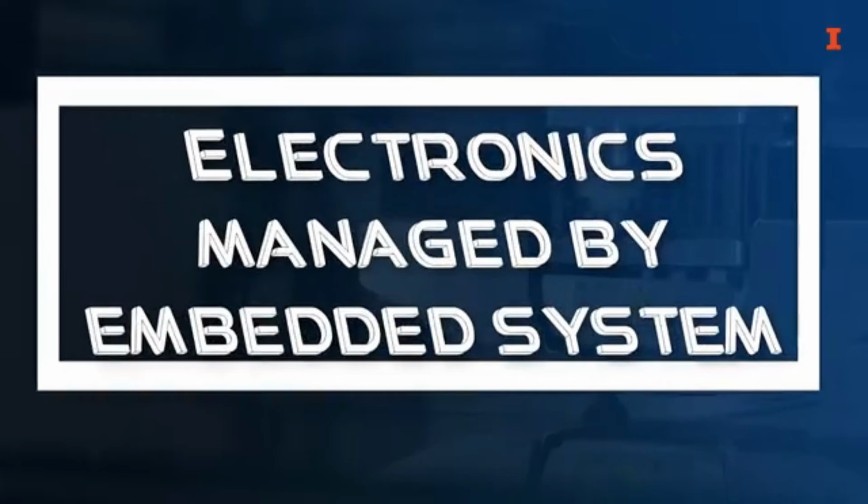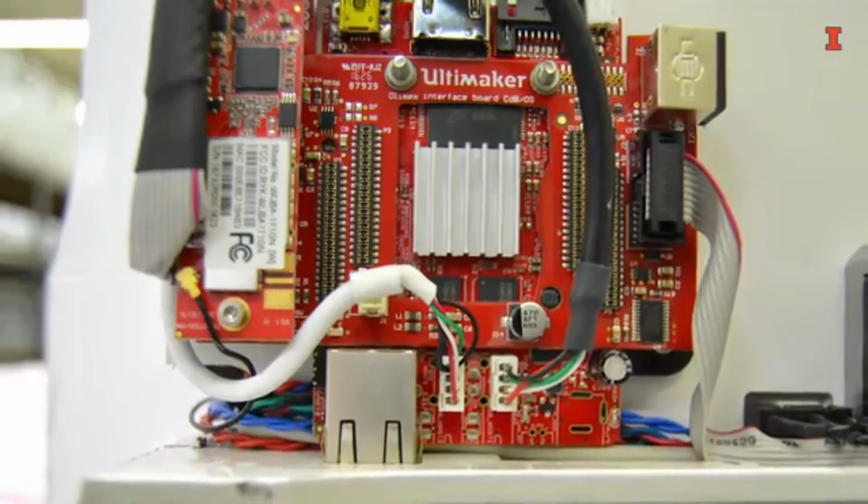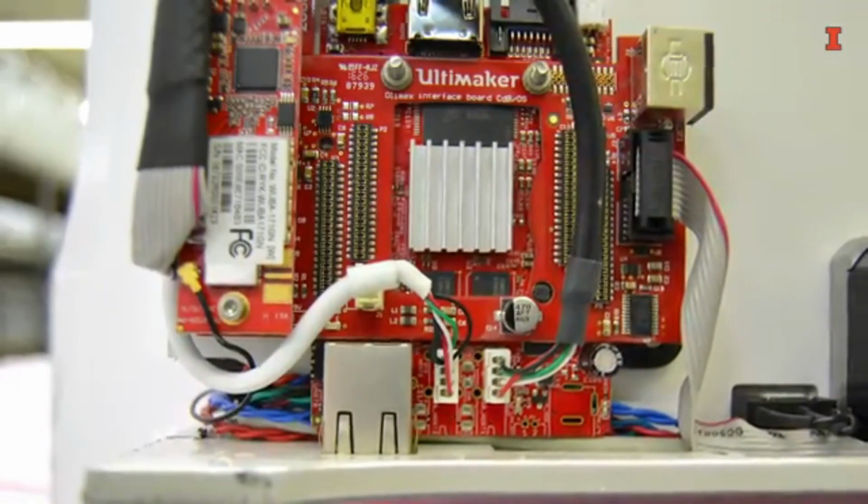In the case of the Ultimaker 2 electronics, the 3D printer control electronic subsystem consists of a main board, power supply, and routing, XYZ stepper motor controllers, extruder motor controllers, heater and print part cooling fan controllers, heater and temperature monitoring, as well as many more like bed heaters, temperature monitors, XYZ endstops, case LED strips, and interface with any daughter boards such as an interface board.